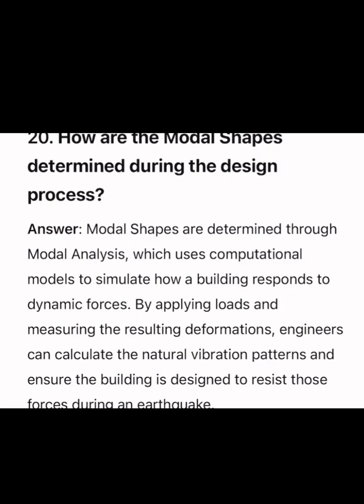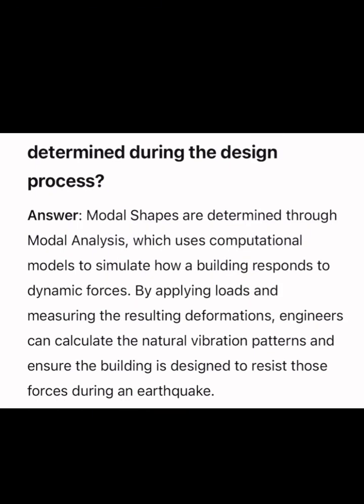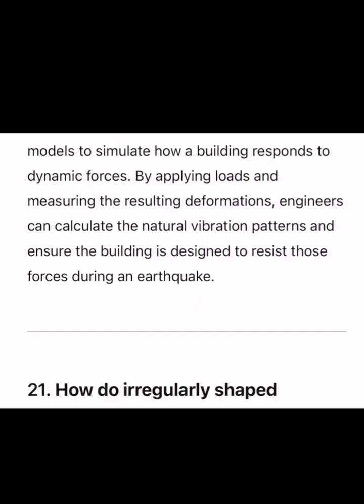How are the modal shapes determined during the design process? Modal shapes are determined through modal analysis, which uses computational models to simulate how a building responds to dynamic forces by applying the loads and measuring the resulting deformation. We need to apply the loads and measure how much deformation is happening, so that engineers can calculate natural vibration patterns and ensure the building is designed to resist those forces during an earthquake.